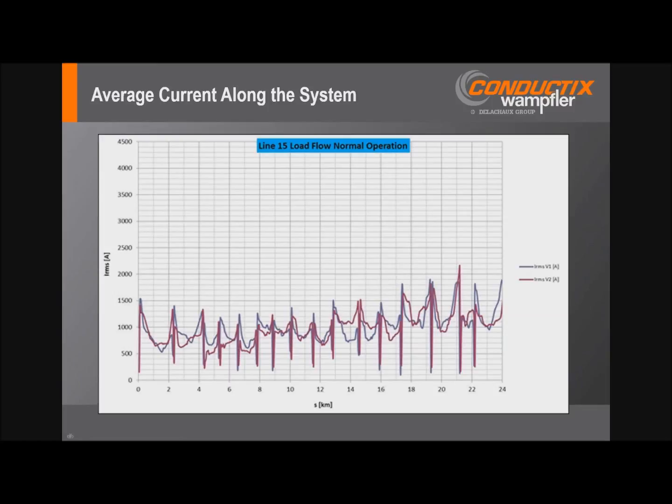How do we manage several power stations on one rail? Do you separate the system into several isolated sections? Essentially what we're talking about here, are these bridgeable or non-bridgeable, and are they connected? Now typically they are isolated, but they're bridged, which means there's an isolation, but as the vehicle is crossing it, it's going to bridge those, but under normal operation, they're not bridged.